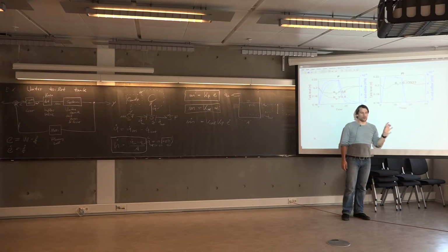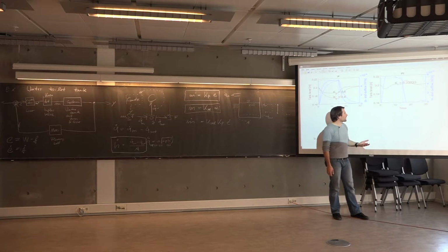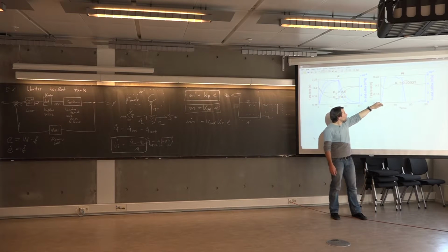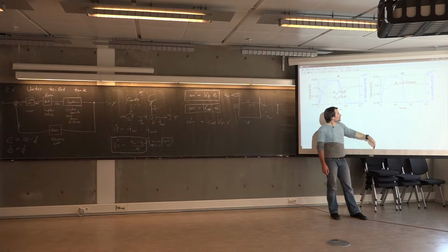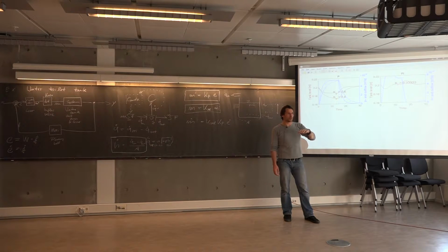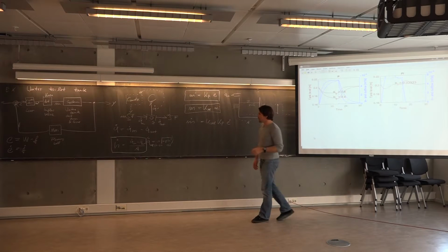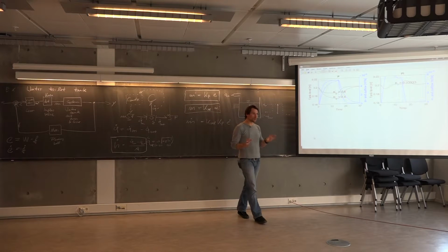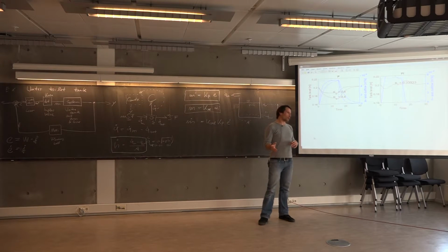this PI controller now is so reactive that it sets the inflow rate negative in order to keep the level constant. And this is very unphysical, obviously, but it's just a consequence of our very crude system. We haven't assigned any constraints to these valves or to the flow rates, right?